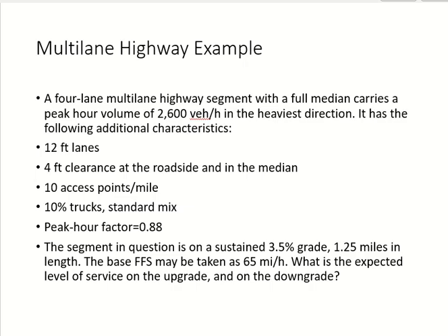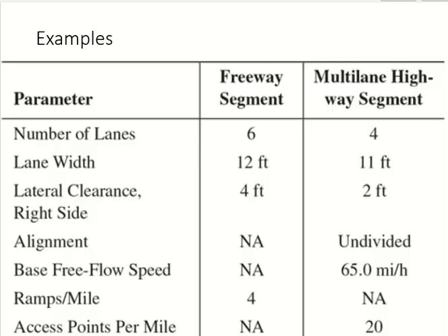Now tell me what was the first step. I told you the first step in all these examples is always the same. Free flow speed. If you don't know it, you have to find it out. But now the free flow speed equation will not remain the same. We have to go back for the factors anyway.